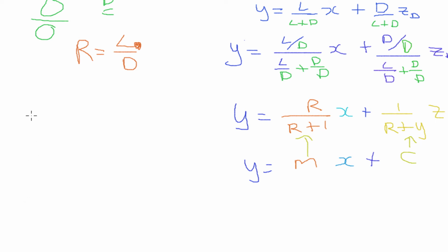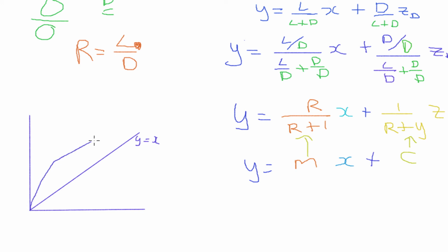The rectifying operating line is the line that highlights the upper section of the column. Now we have our graph here, and we have our y equals x line, our 45-degree line, and let's say we have an equilibrium curve as shown in the diagram that I'm drawing.